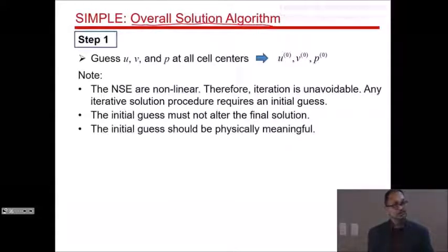Now sometimes that guess may not work, but for the most part it works fine because the moment one of the control volume faces sees an inlet velocity, those zeros get replaced. But if you have a problem where zero velocity keeps everything zero, nothing changes, then maybe it's difficult to jumpstart. You may have to start with some value. But for the most part, zero works fine, especially for pressure.